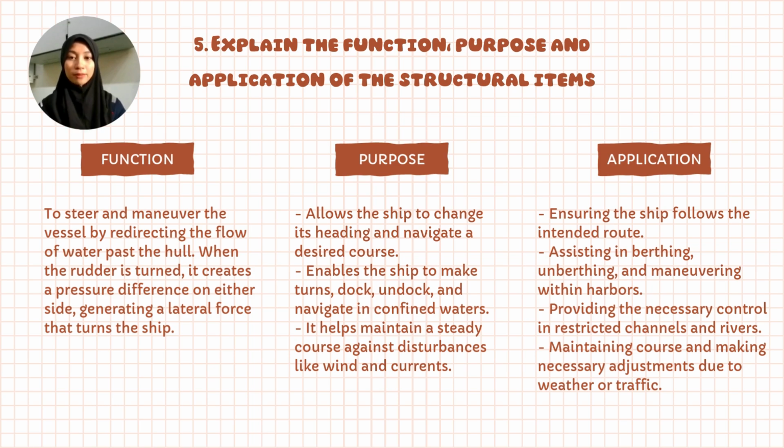Okay, I will explain about the function, purpose and application of the rudder. Okay, for function, to steer and maneuver the vessel by redirecting the flow of water past the hull. When the rudder is turned, it creates a pressure difference on either side, generating a lateral force that turns the ship. Okay, for purpose, to allow the ship to change its heading and navigate a desired course, enable the ship to make turns, dock, undock, and navigate in confined waters. It also helps maintain a steady course against disturbances like wind and currents.